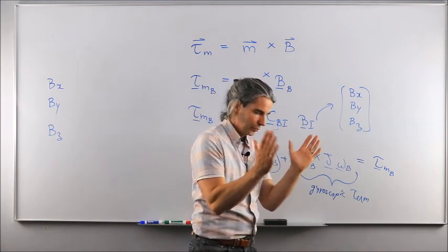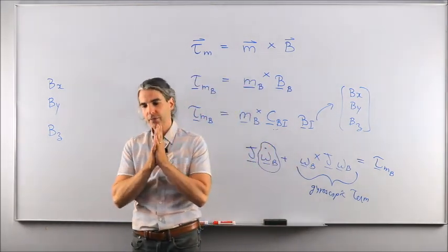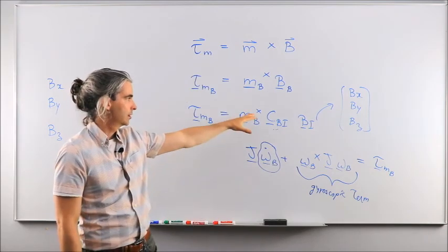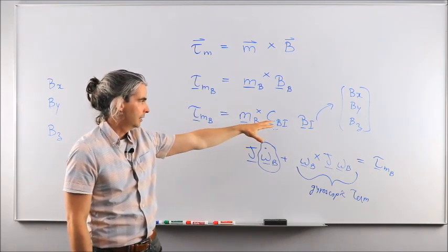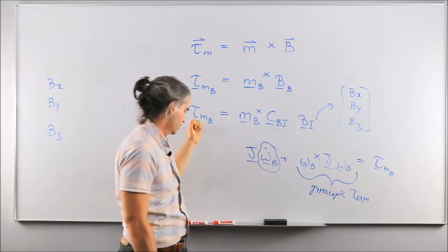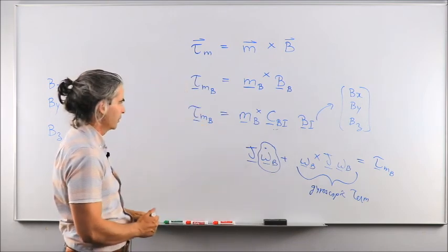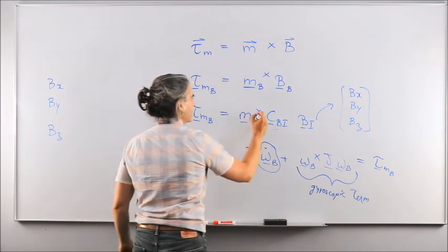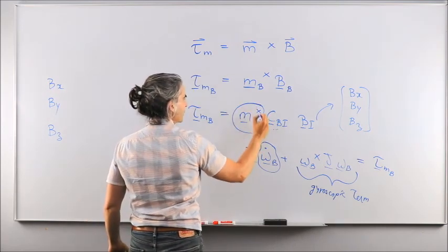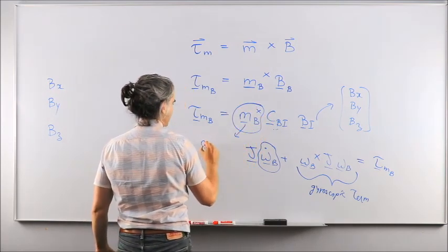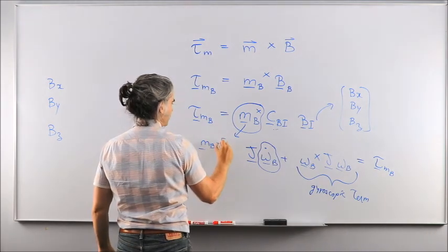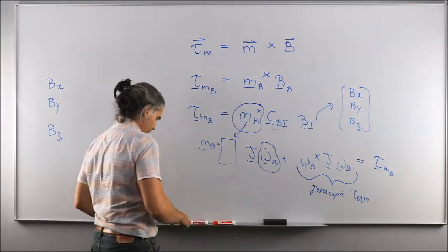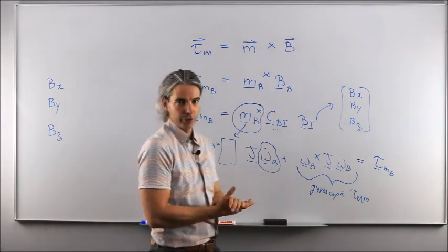Great. So 3 ways to model the Earth's magnetic field. And then based on that, just do simple skew-symmetric multiplication here to get the torque due to the magnetic field of the Earth into the body fixed reference frame. The last thing I didn't talk about is this. So this M_B as a column matrix will be provided to you by the electronic engineers working under your supervision.